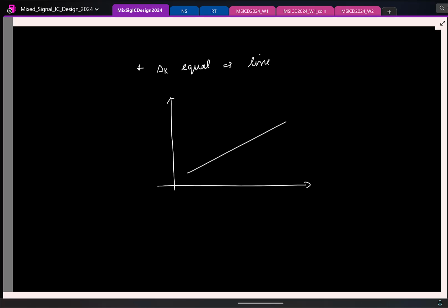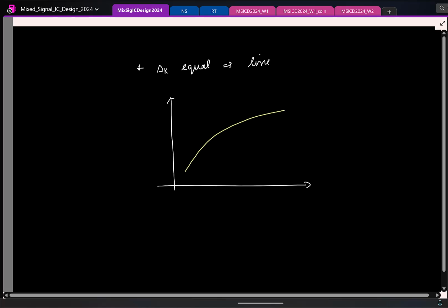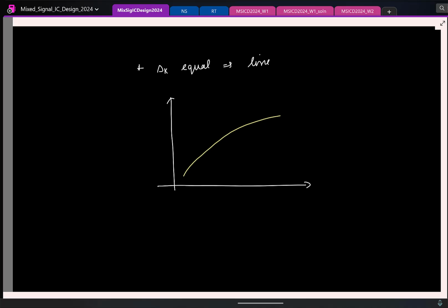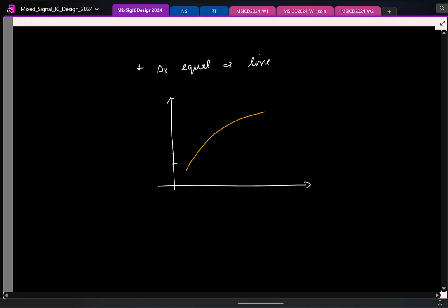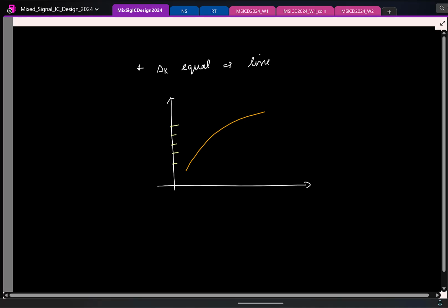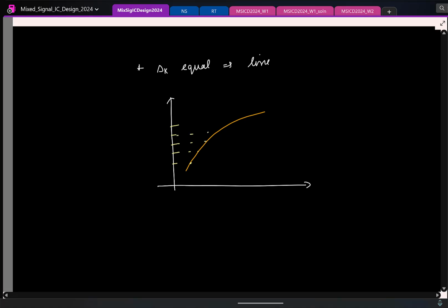So to this quantizer, if I feed in a sinusoid, I will not see technically the harmonics. Now if I have a nonlinear ADC due to circuit nonlinearities, I will basically have some nonlinear characteristic like this. That is, if I connect all the transition voltages, I will no longer have an exact straight line. I am grossly exaggerating in my drawing. You will get a nonlinear curve like this. So here if you actually go and sketch this, let us say these are different codes, you will basically have something like this, the characteristic.